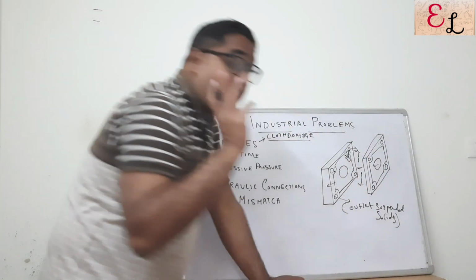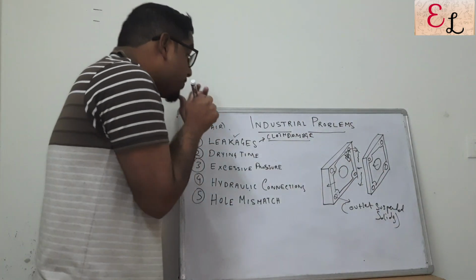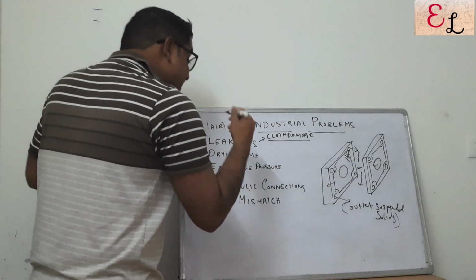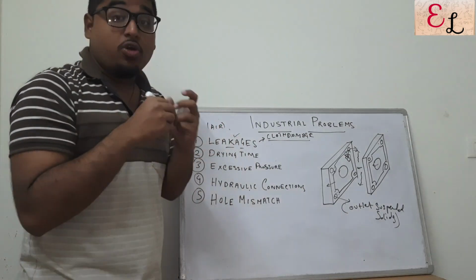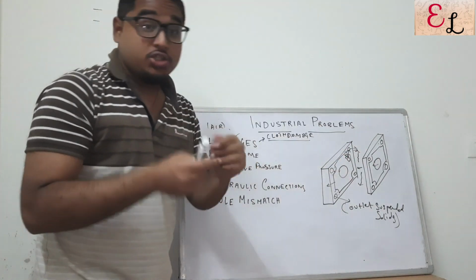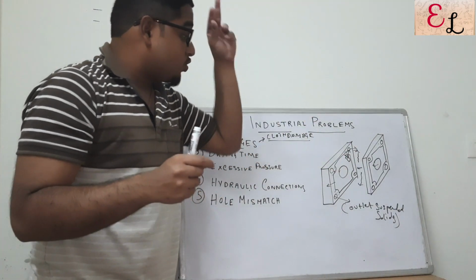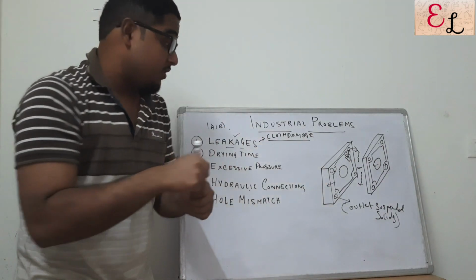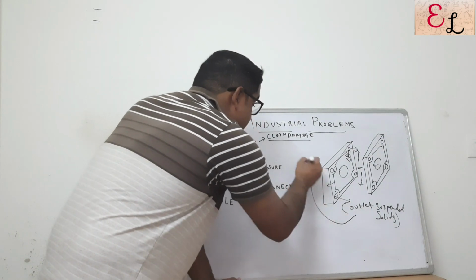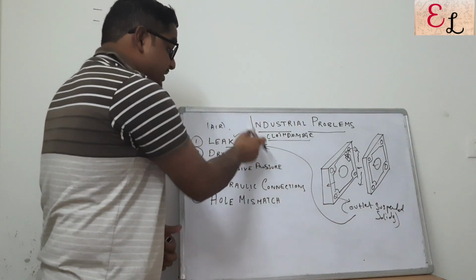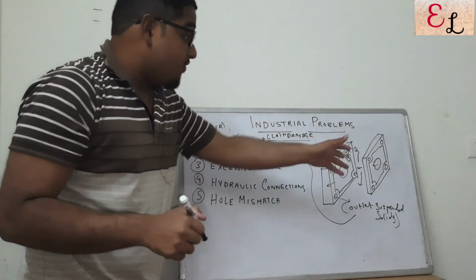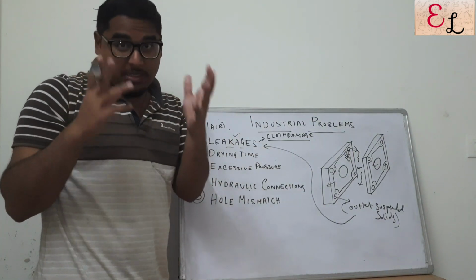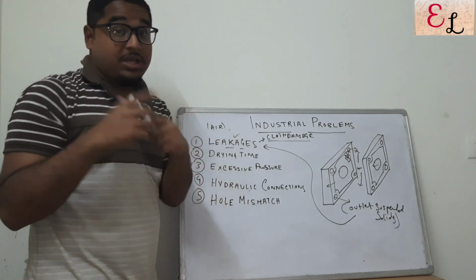That the filter press operation is not served, and this is one of the major problems that industrial filter presses face due to excessive leakages in the cloth, because of which the solution passes through that leakage point and through the outlet with unseparated solids. So this outlet suspended solids is directly linked to leakages. There is a cloth leakage but not a visible one, and you would find that this is a major problem in industrial filter presses when the cloth has been damaged.